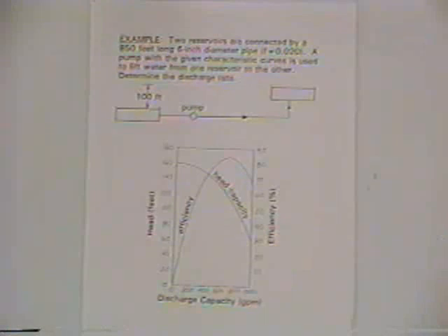Well, when you think in terms of pumps and their capabilities, there's a relationship, again, between head and discharge. If the pump has to work against a small head, it can pump a lot of water. But if you're asking the pump to lift the water some enormously great vertical distance, it's not going to be able to do so at a large discharge rate.